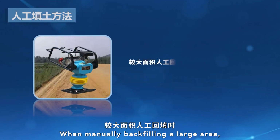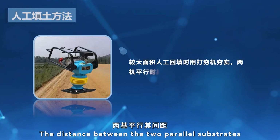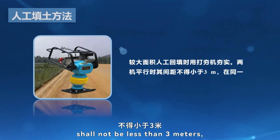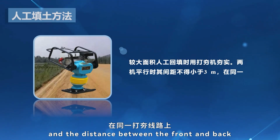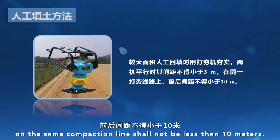When manually backfilling a large area, we use a mechanical rammer for compaction. The distance between two parallel compaction lines shall not be less than 3 meters, and the distance between the front and back on the same compaction line shall not be less than 10 meters.